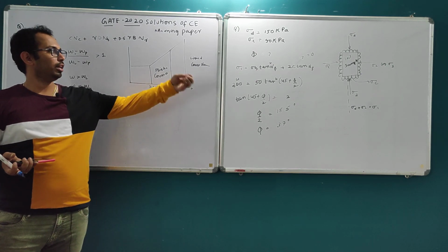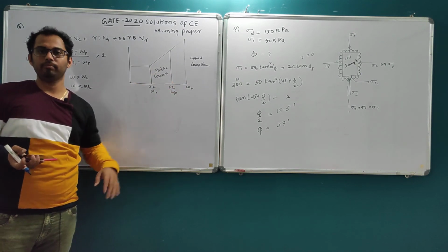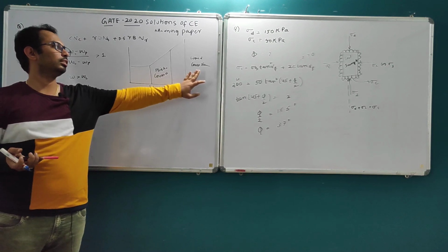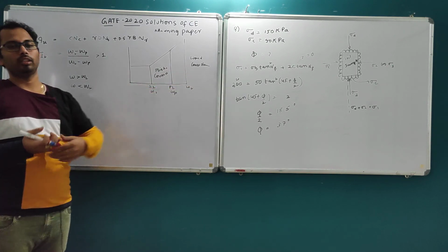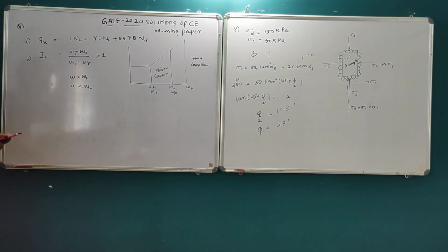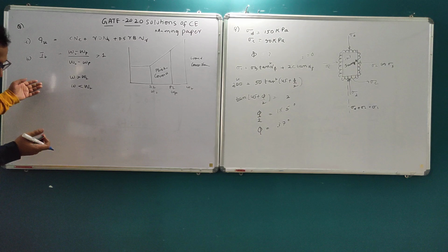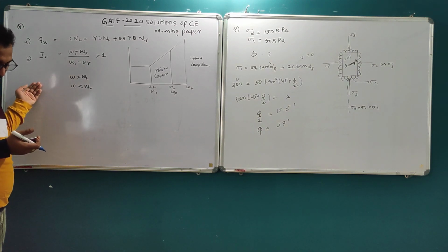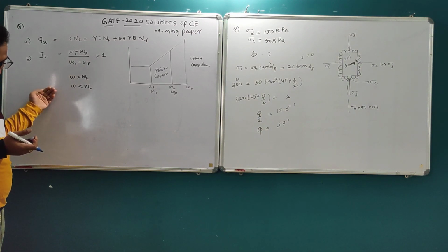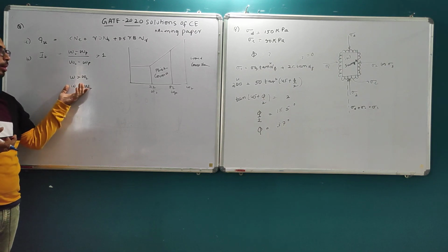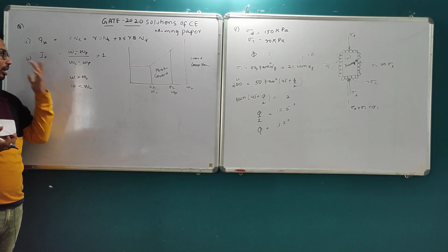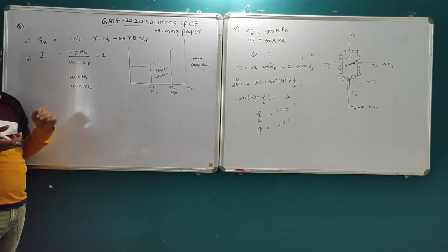Beyond the liquid limit, it behaves like a liquid completely. So plastic consistency here is impossible. So that is why that is the wrong answer. For the rest of the options, it is a waste of time analyzing them. It is clear that a clay deposit with a liquidity index greater than unity being in a state of plastic consistency is a blunder. So that is why we can directly solve it using option B.